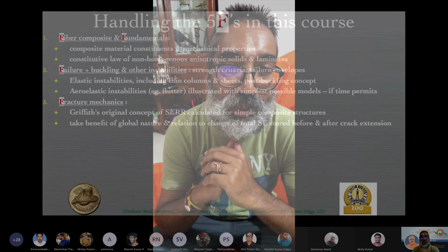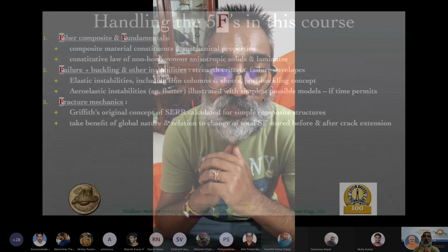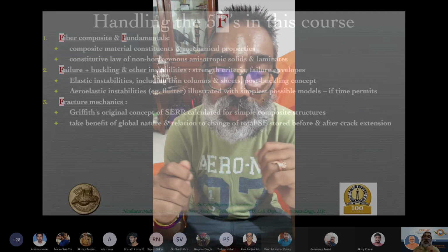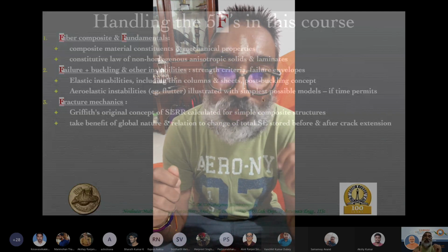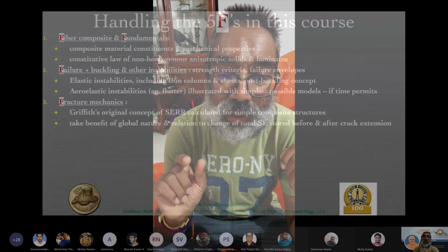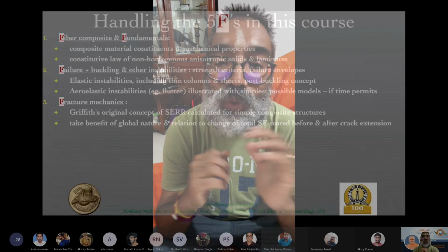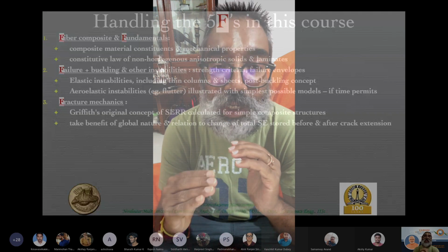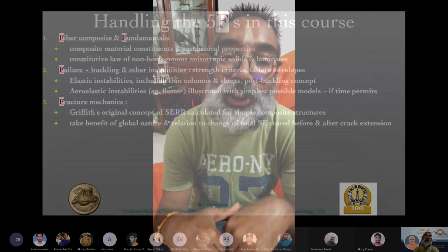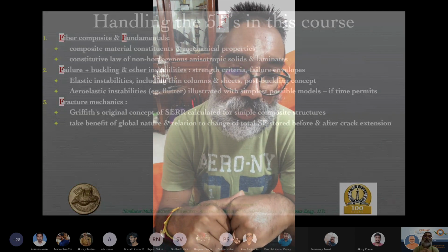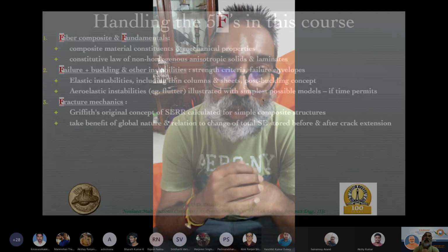For example, the typical situation you could have is a rubber kind of material, where as you start extending, the amount of force you need to extend becomes different from what it was even to accomplish a unit strain. So this change in the load or stress required to create an additional unit strain is basically a changing E. So in other words, E becomes a function of epsilon. So E is no longer a constant. If you write sigma, it generally becomes a function sigma of epsilon.